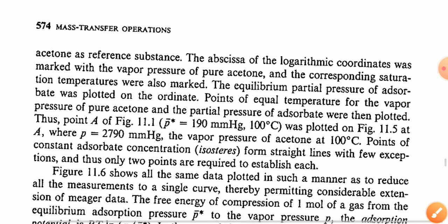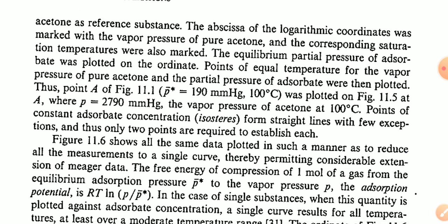Now the discussion part is again acetone as a reference substance. Acetone as a reference substance: the abscissa of the logarithmic coordinate was marked with the vapor pressure of the pure acetone, and the corresponding saturation temperatures were also marked.